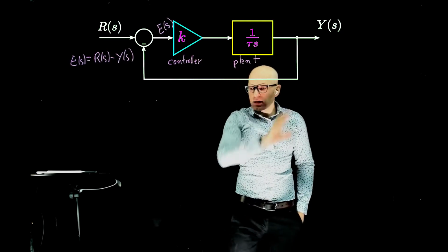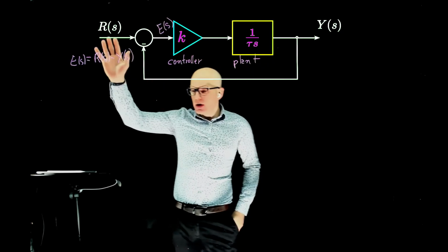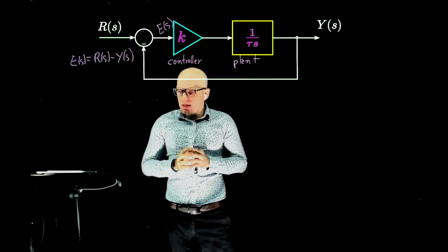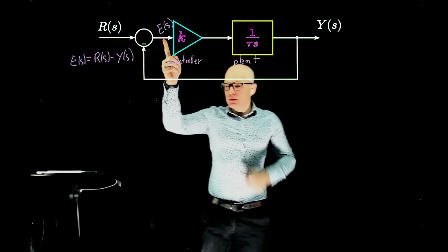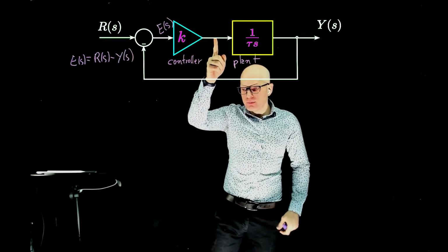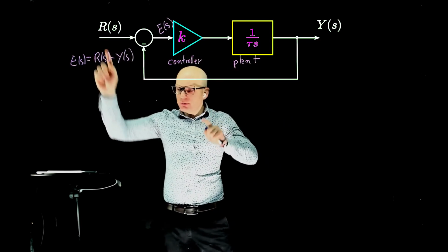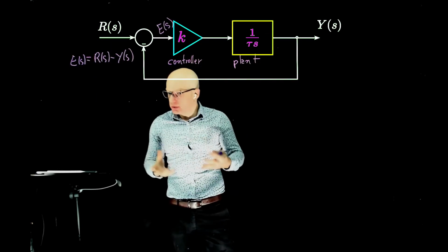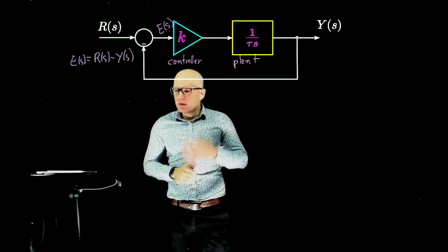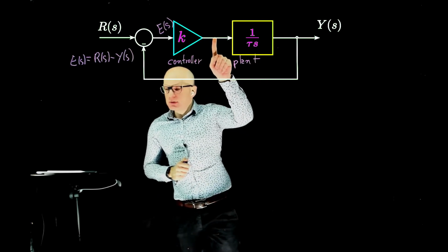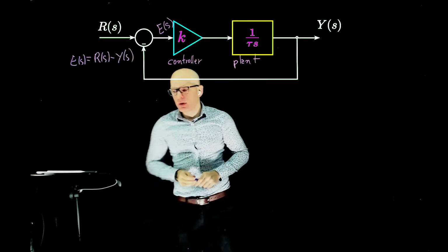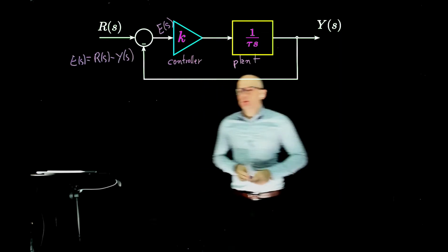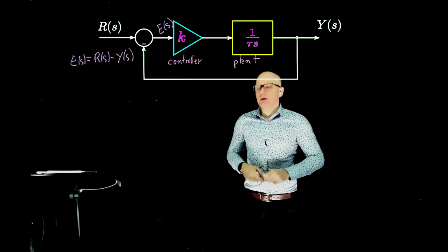If we are exactly where we want, that is, there's no error, the desired input and the desired output are exactly the same, this is 0, we don't open the valve. So long as there is a small difference between the desired and the actual value, we multiply that by a constant that we need to design, and that will give then the amount of opening we apply to the valve. Okay, and this system now continues to operate like that.